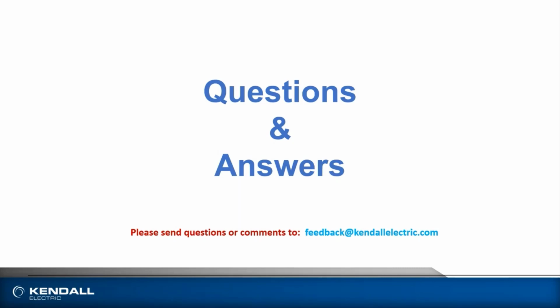Okay, thank you, Rob. Can one Micro 800 talk to another Micro 800, and how is this done? If that's going to be done, it's going to be done through explicit messaging, EtherNet/IP-wise. Yeah, I believe that Rockwell has a document that goes over how to set that up. It's a quick start guide, QS002, if I'm not mistaken.